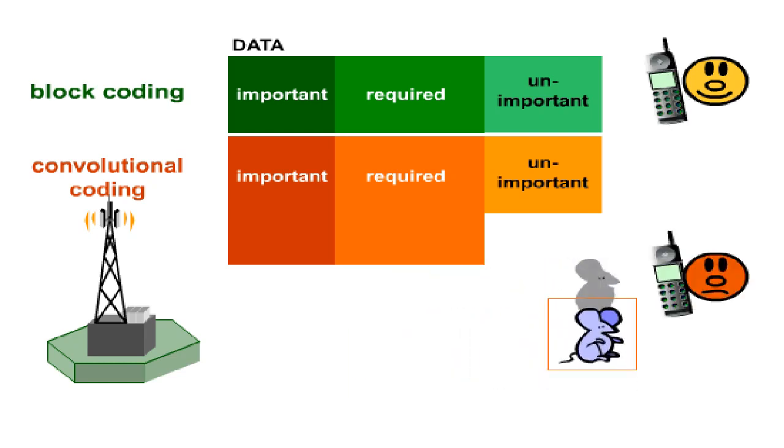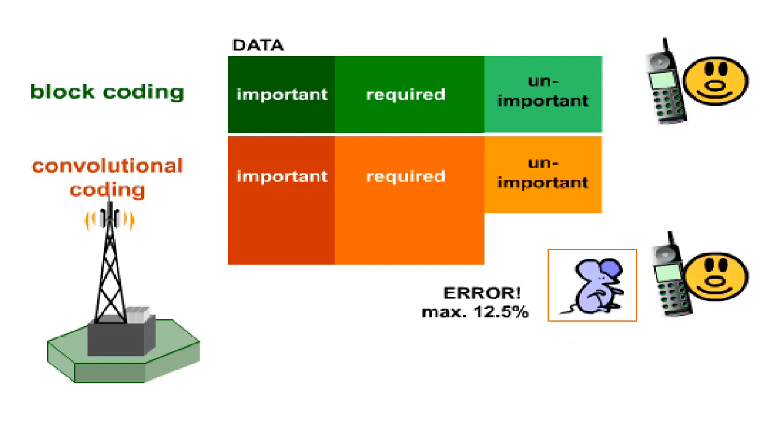This procedure allows to fully compensate bit error rates of up to 12.5% in the secured relevant data. Channel coding increases the bit rate necessary at the air interface from 13 to 22.8 kilobits per second.